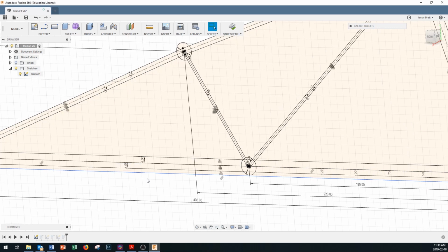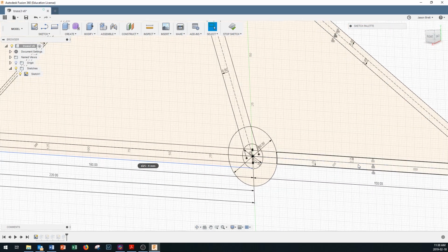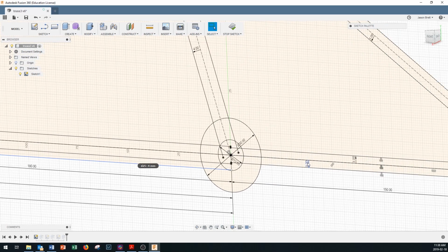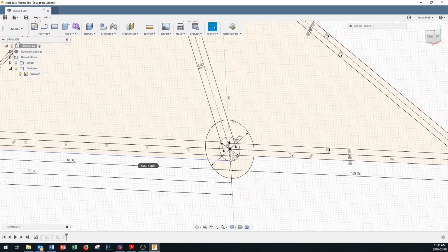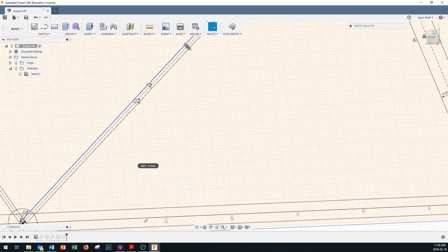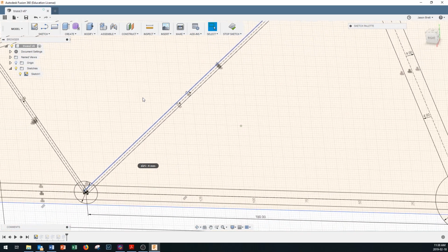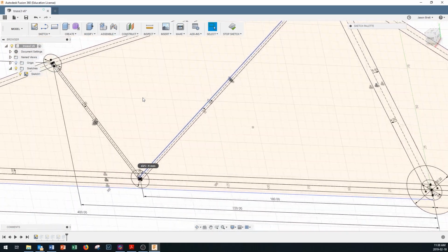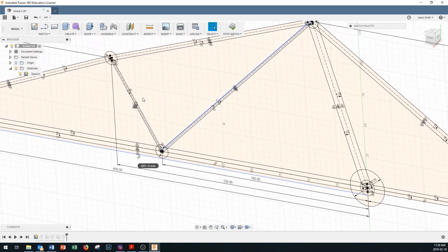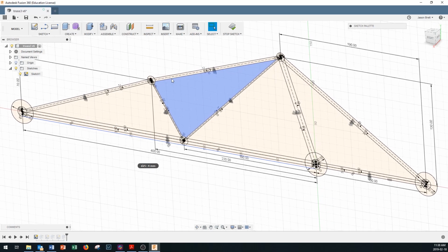Now, I'm keeping everything symmetric. Technically, there's no reason why they need to be perfectly symmetric. This one back here can probably come down. Now, in our simulation, we don't show any loads in there because of the way I've pinned the constraints in here, that's maybe a bit egregious. Now, these ones are sitting at 1 millimeter by 1 millimeter. We could take them down smaller, but the laser probably won't cut much thinner than that. You've got to remember the laser has about a 0.5 millimeter kerf, so everything the laser cuts comes out slightly smaller than what you see on here.